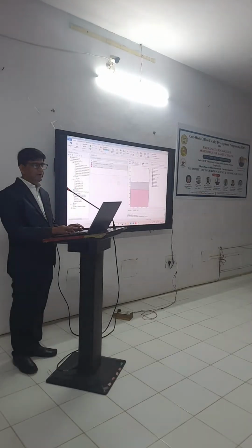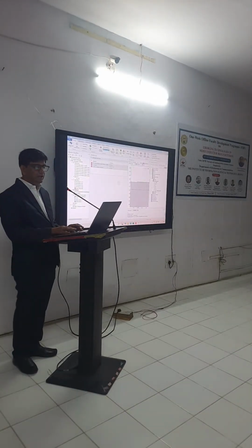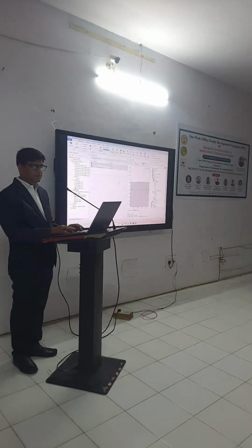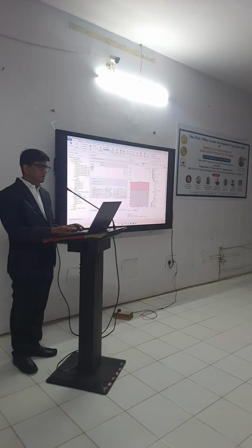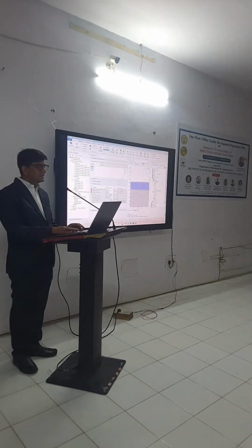I will go to material and go into MEMS. In this MEMS I have a material, semiconductor, and what I need is ZnO. So where will I get this ZnO? In insulator. So this is zinc oxide. I will right click and click here. So this is my ZnO layer. Okay. After that, we require this property.